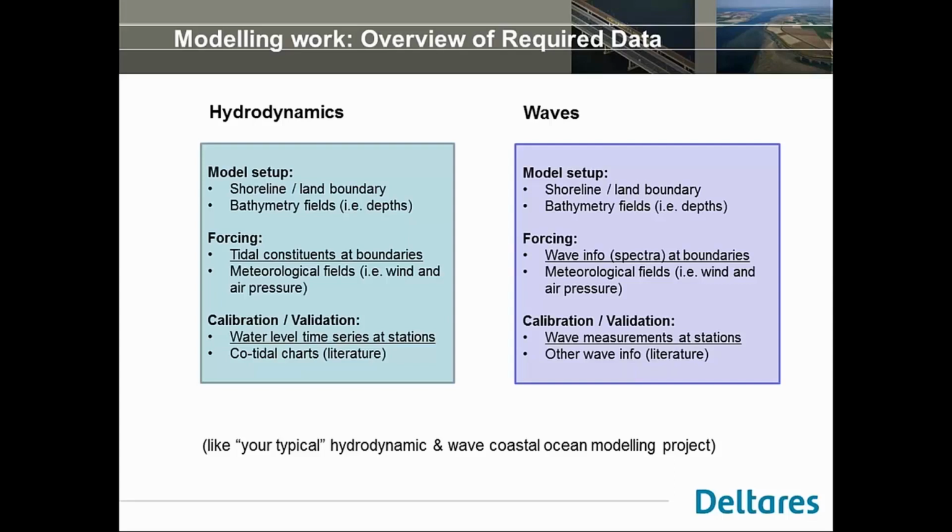In this case, I'm following on the left hydrodynamics. You need tidal constituents at the boundary, but also at the surface meteorological fields. And then you want to have data for calibration and validation. So you should gather, well, in this case, time series of water level at several locations. But if you can get your hands on literature showing co-tidal charts, that's also quite handy.